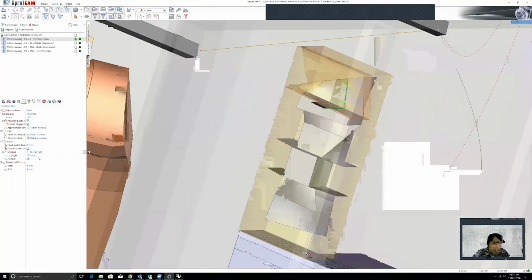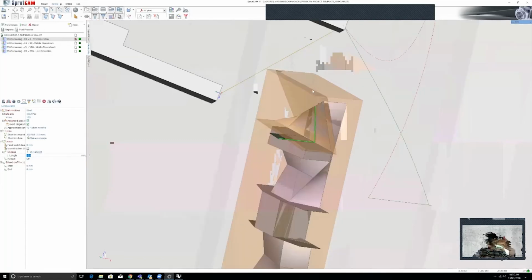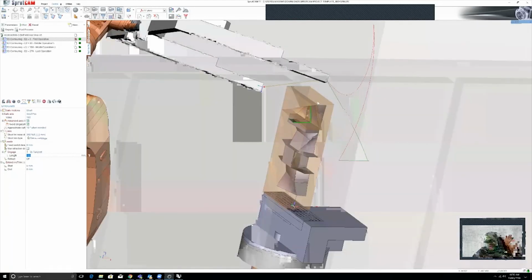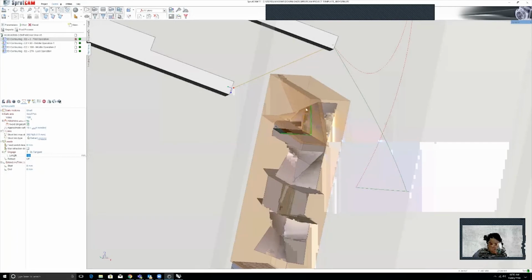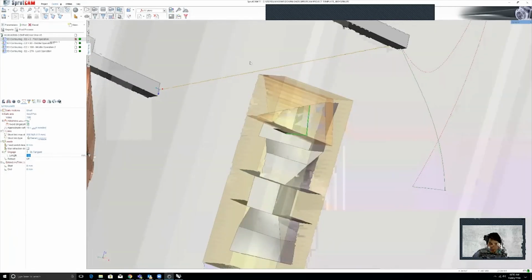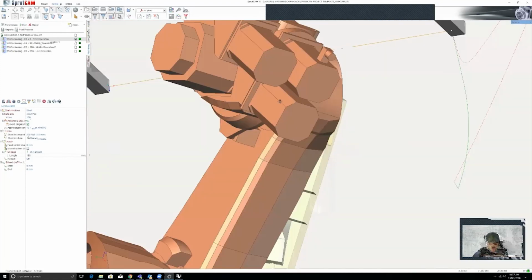And I'm going to make this a little bit higher, because remember, when the robot is engaging the foam, it's cutting at a cut speed, which is much slower. You can imagine everything here in red is the rapid speed. So it's going to approach your block at quite a quick speed before it gets into that engage speed, the 150 that we've assigned. And I think this is a bit too close for the robot to suddenly get so close very quickly to the block. So I'm going to extend this even further to maybe 180, and then run it. I think that's a little safer for us.